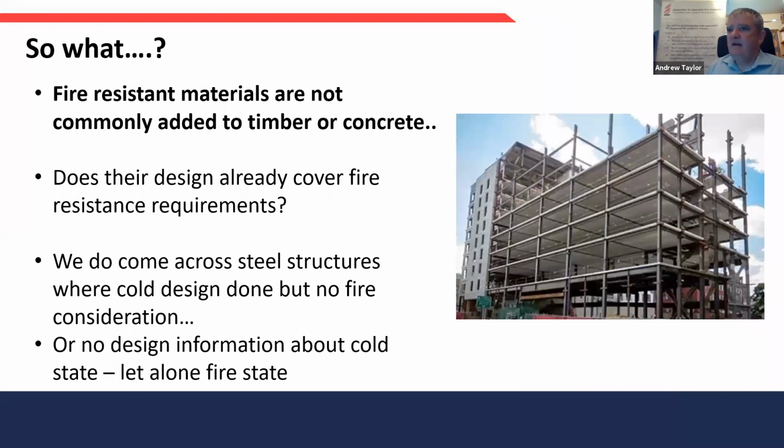Well, fire resistant materials are not commonly added to timber or concrete. Their design already covers fire resistance requirements, but within our ASFP TG groups, and with people I talk to who are allied to those, both as installers and as manufacturers, we sometimes come across steel structures where the cold design's been done, but there's been no consideration of what's going on in fire, or maybe the fire design has been done. This is the more common thing, but the design information doesn't come down the contractual chain.